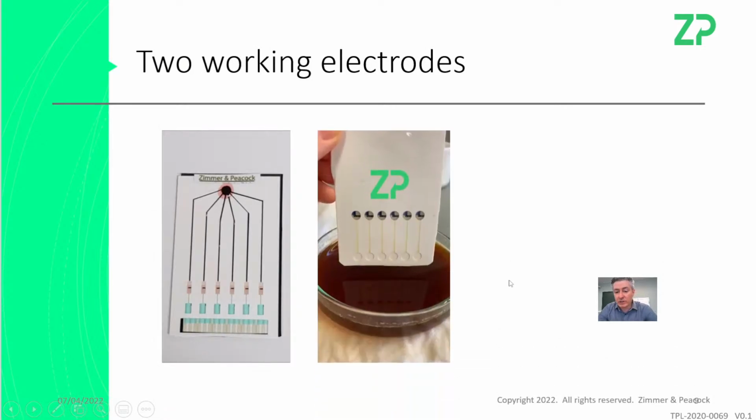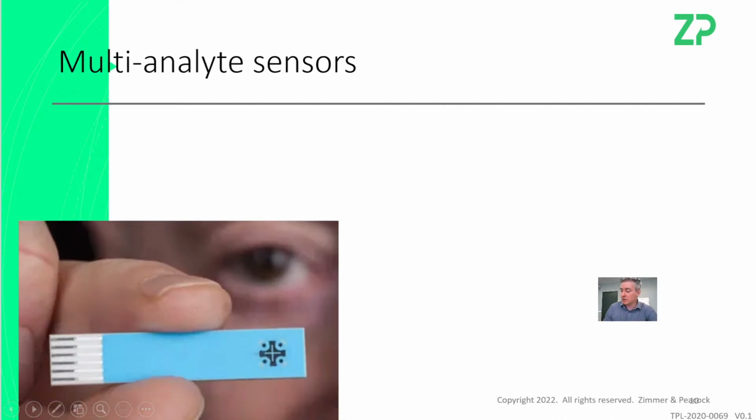What I want to say is, this is the way we do it. Contact us, consult with us, commission us, but we put essentially single electrodes into a credit card format so that we can manufacture one of the sensors, make sure it's in high yield, manufacture another of the sensors, make sure it's in a high yield, and then bring the 2 sensors together into a product. And therefore, the overall final assembly will still be in high yield. Otherwise, you try to do it all in a single row and you'll end up with very low yield. So be very, very careful.